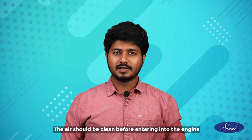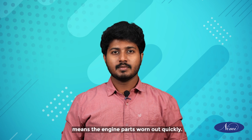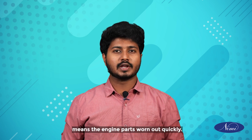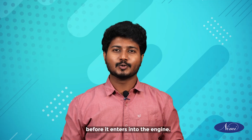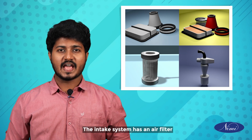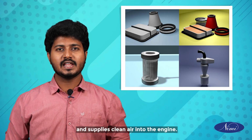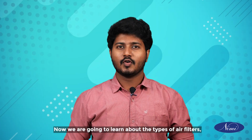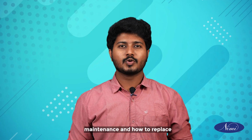The air should be clean before entering the engine, or the dirty air affects the engine components, meaning the engine parts burn out quickly. It is very much essential to clean the air before it enters the engine. The intake system has an air filter which filters the dust particles in the air and supplies clean air into the engine. Now, we are going to learn about the types of air filters, maintenance and how to replace them.